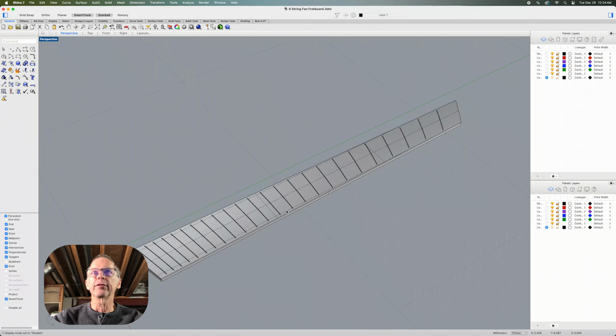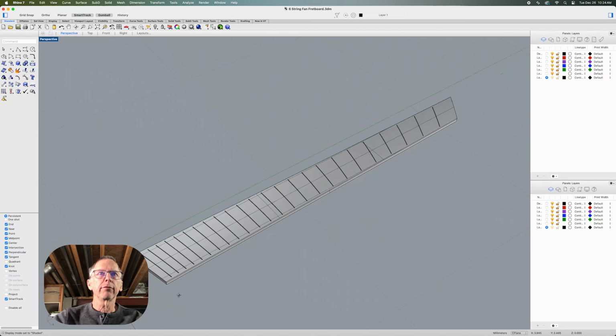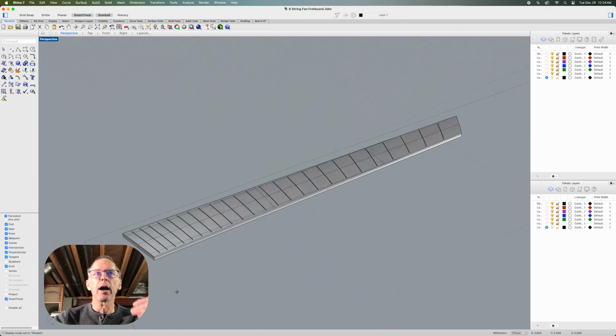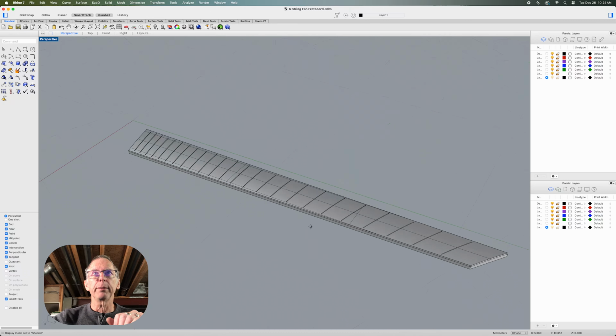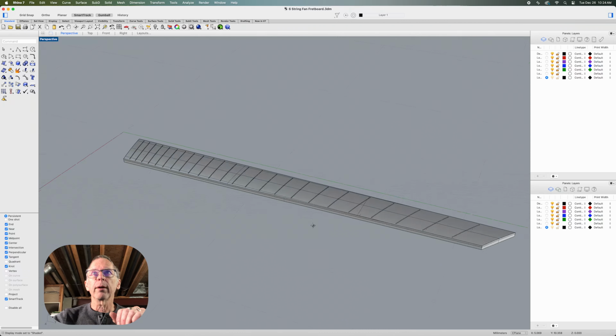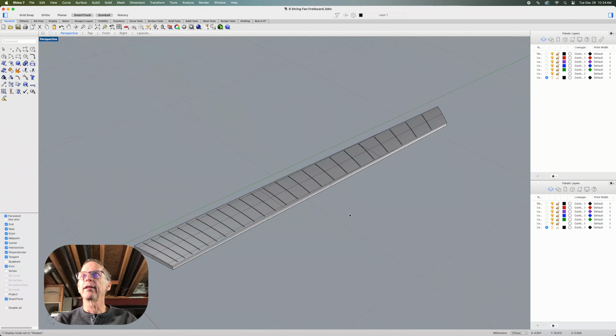And for this particular design, the scale lengths are, for the low E, 28 inches. For the high E, it's 25 inches. And then for the fretboard radius, I'm doing the compound radius, and at the heel, it's 16 inches. And then at the nut, it's 10 inches. So I'll be creating that with this file. And that's what I'll be using for the fretboard on this 6-string multi-scale fan fret guitar build that I'm currently